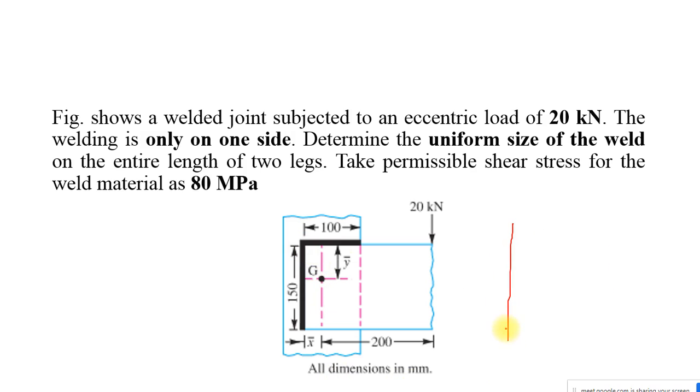If I want to tell where exactly, you can see here it is something like inverted L, where for y-axis the line is here and for the x-axis is somewhat here, where both the intersection I am having a G here, center of gravity. Okay. So it is very very clearly understood that both x and y are not at the center of the weld.